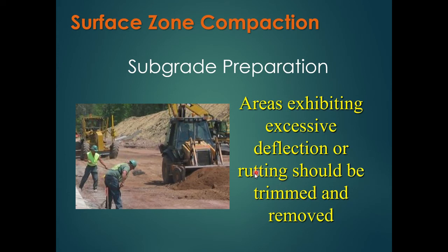So rutting, so we can have rutting, right? We want permanent rutting, but we don't want it too deep. If it's too deep, that means the underlying layers below 12 inches have not been compacted correctly. Because remember those nuclear density tests, they can only measure to a depth of 12 inches. That's it. So if you show up and they're done placing all the fill and you measure the top lift, that's all you're measuring is the top 12 inches. It doesn't mean they compacted anything below 12 inches or deeper. Okay.